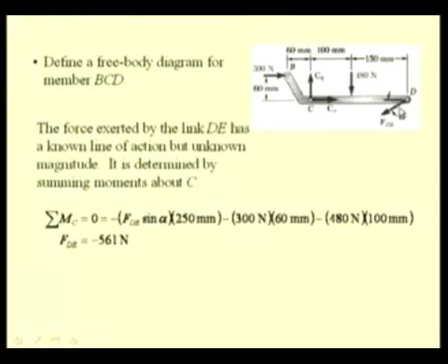Since we have originally assumed the force to be tensile in nature, but since the answer has turned out to be negative, the force is of compressive nature. Now, let us move to the other multi-force member that we have in this frame.